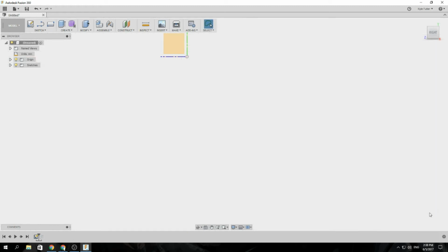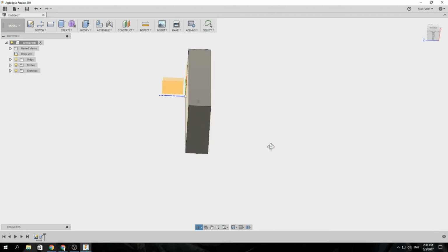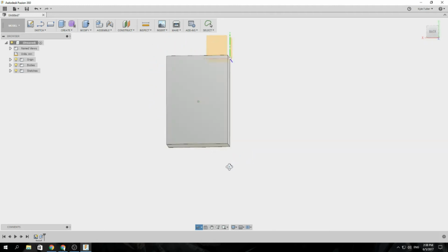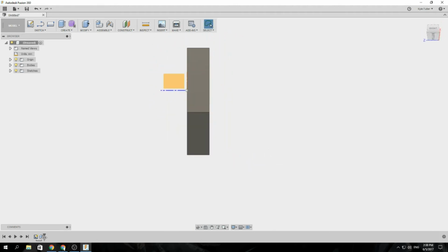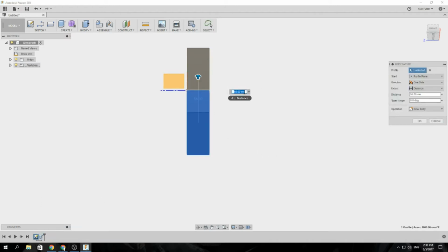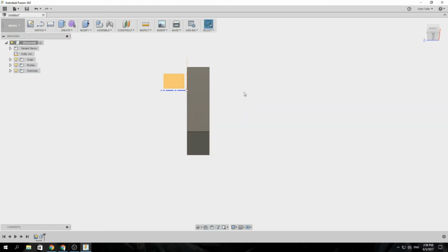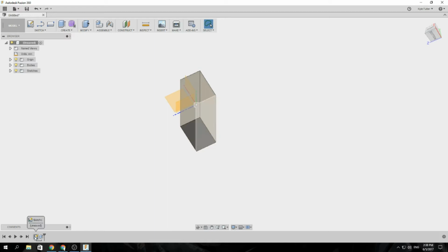And if we click stop sketch and we go back to the front of our timeline, oh, look at that. Our box has changed to those dimensions. And then say we want to edit that extrude, and we want to make it 80 by 20 by 30. And now you have your box. And that is the basics of parametric modeling, meaning you can go back to your timeline and change features. You can't add something new, you can only edit.